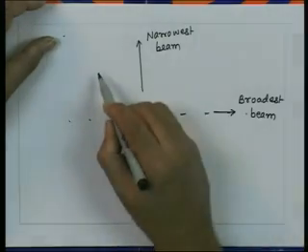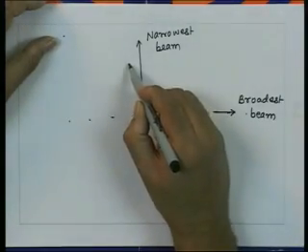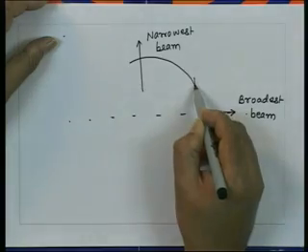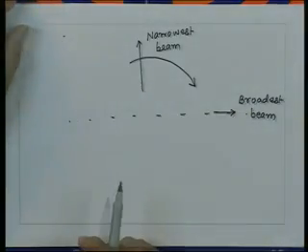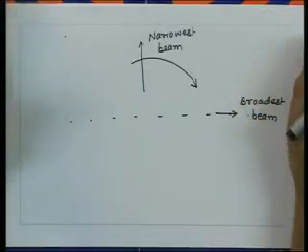So, the beam width essentially increases as we change the direction of the beam from the broadside to the end fire. This is very important because whenever we use the antenna array in an environment where we want to scan the beam by changing electronically the phases, what is called the phased array antennas, the beam width does not remain constant while scanning the antenna.